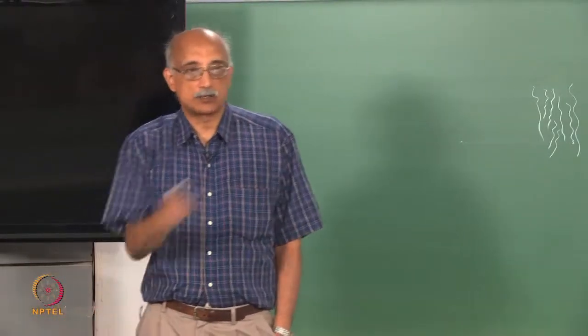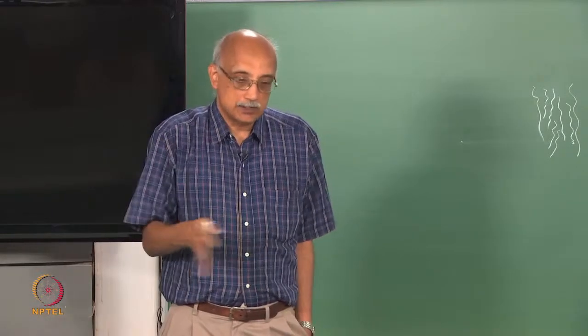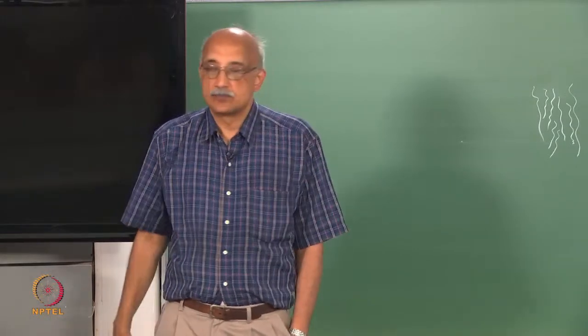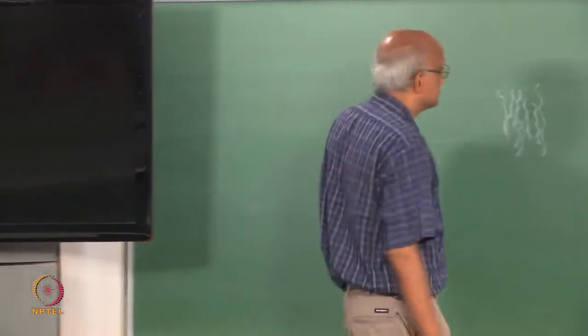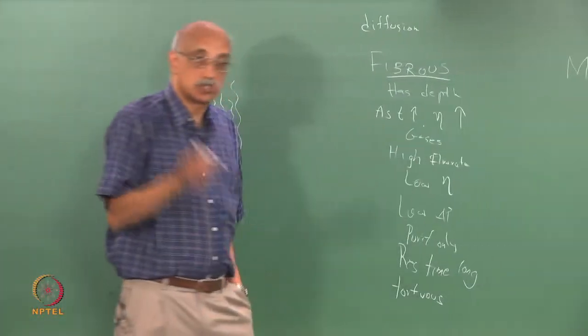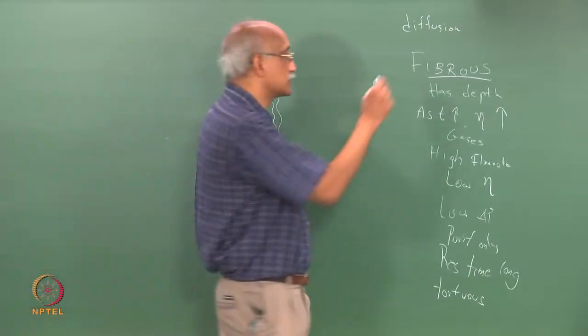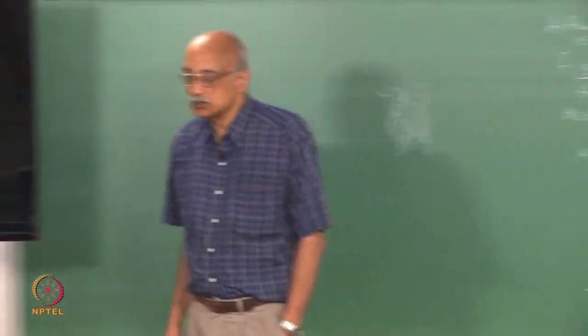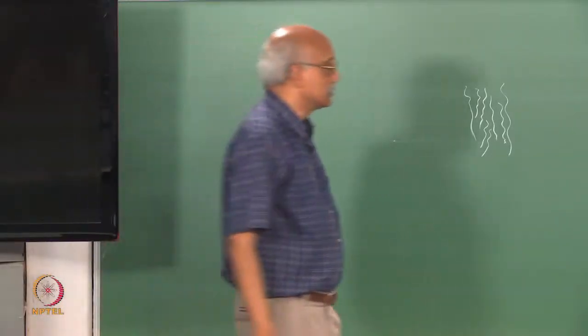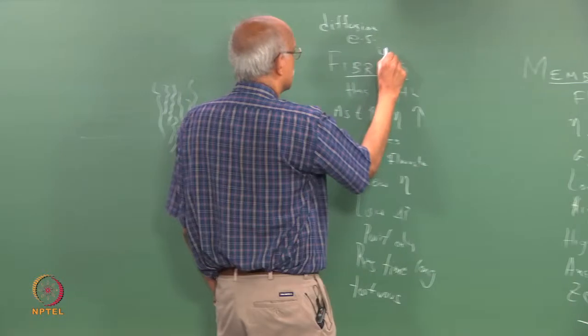You are expecting the particles to diffuse around inside this filter medium until they get captured. You can also induce charge in the fibers, you can use charged fibers. So, you can use electrostatic effects to some extent. Interception is possible.